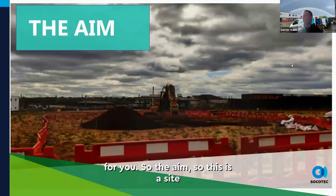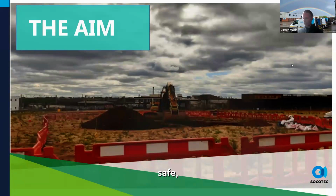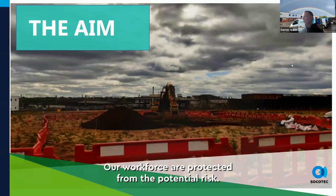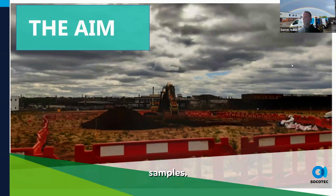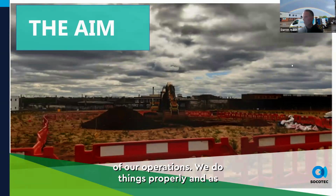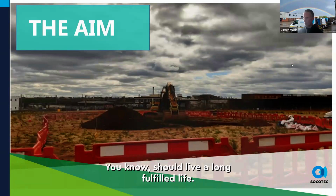So this is a site where we've finished. The aim is that we're carrying out the work safely, we're not impacting off-site receptors, and our workforce are protected from the potential risk. You can see the red samples. We have an exclusion zone. We're carrying out asbestos air monitoring downwind of our operations. We do things properly and as robustly as possible, and our workforce go home safely and are not exposed to risks, so they can live a long, fulfilled life.